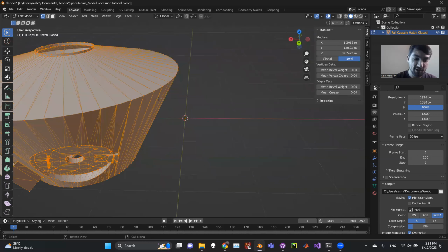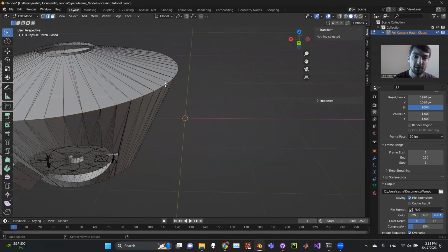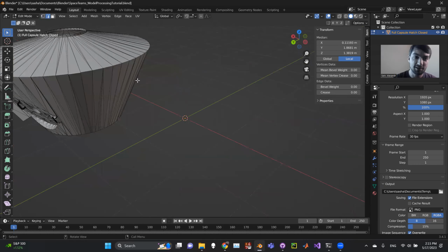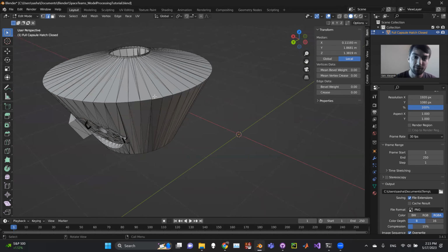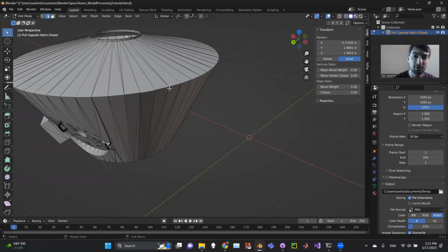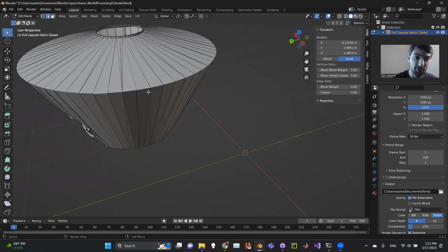We're currently in vertex selection mode, and you can see that up here. Let's go to edge. You can do that with 1, 2, and 3 on the top of the keyboard, not the number pad. If you just hit 2, we can then deselect everything with Alt-A, and then holding Alt, you can left click. It didn't select the full ring of edges, which is kind of unfortunate for this model. Instead, we got just the one.